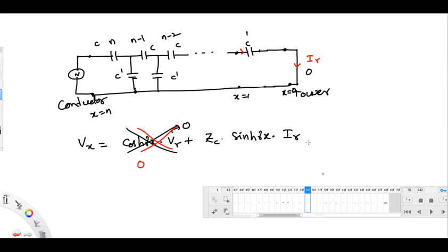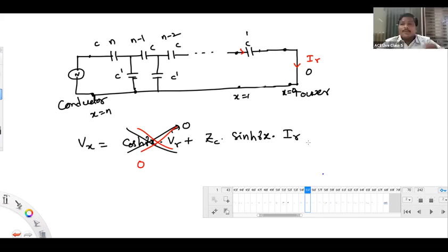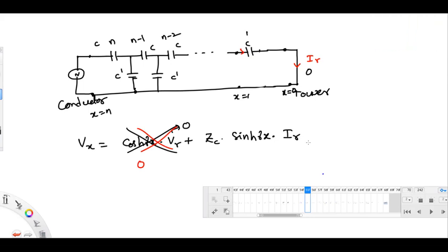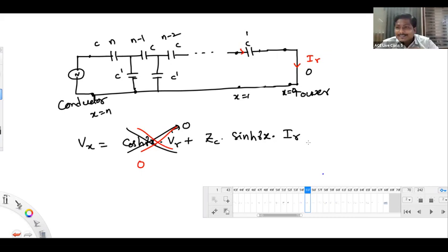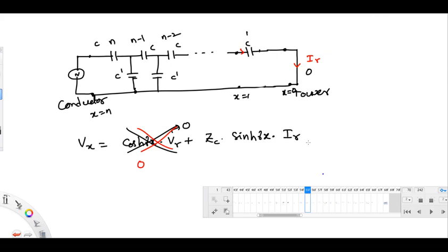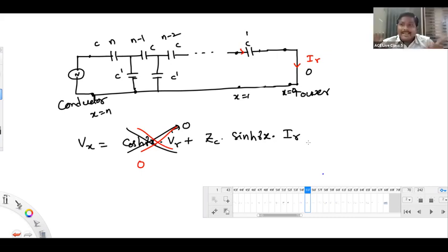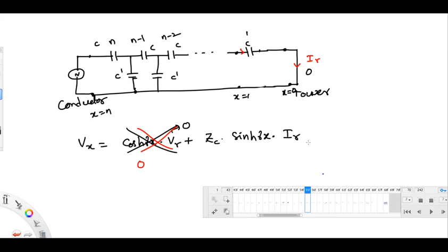For example, at some place, I am observing continuously there is an under voltage. So at that place, we decide to keep a capacitor bank only. That is the way we decide to keep a capacitor or a reactor. For example, at a certain bus, always I am experiencing higher voltage, so let's keep a reactor there.